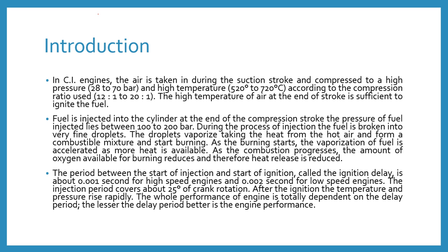The period between the start of the injection and the start of the ignition is called the ignition delay, which is about 0.001 second or 1 millisecond for a high speed engine and 0.002 second or 2 milliseconds for a low speed engine.